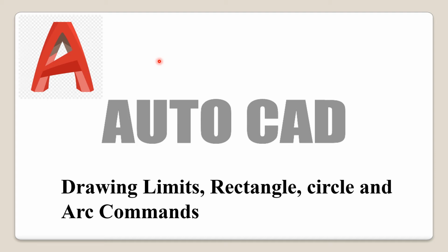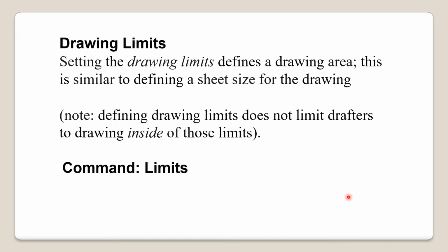Welcome to the AutoCAD next lecture on drawing limits, rectangle, and also we will discuss the polygon command and the circle and arc commands. Drawing limits: setting the drawing limits defines a working drawing area. This is similar to defining a sheet size for the drawing, for example drawing sizes like A4, A3, A2, A1 and A0. We can set up the drawing limits for our drawing purpose.